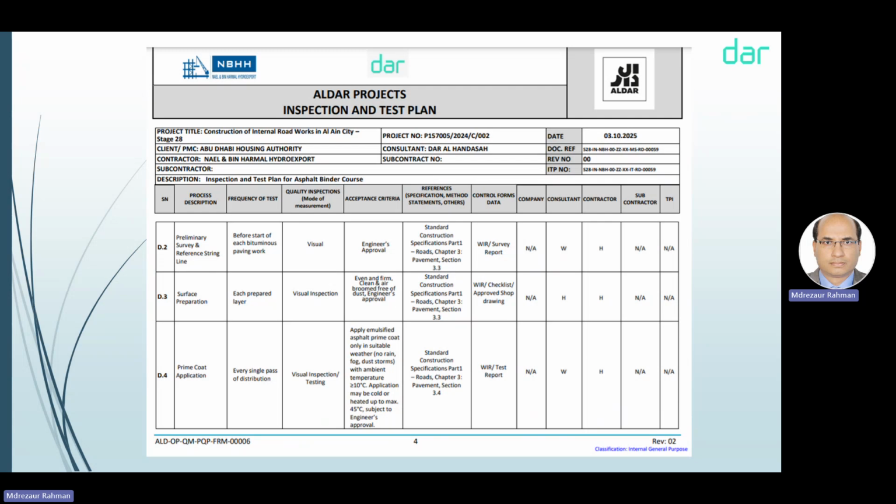Two things actually. You are checking the level, but who is checking the cleaning? So are they submitting any WIR for surface evaluation? It must be. So they're applying directly? Who will ensure that there is no dust? They must submit. This is submitted by the contractor, not by us. As per contractor submission, surface evaluation is the whole point. They must submit. Maybe for the mock-up, we will see.